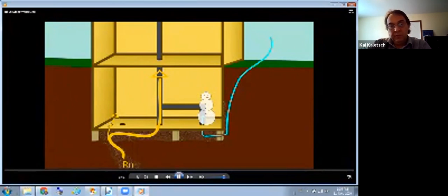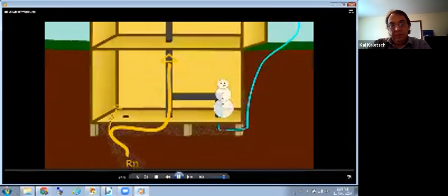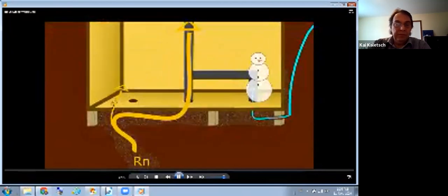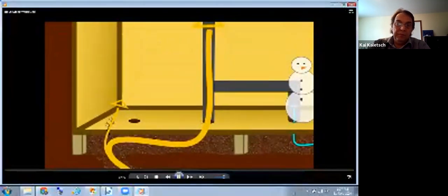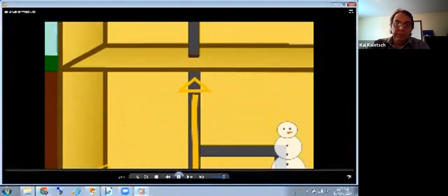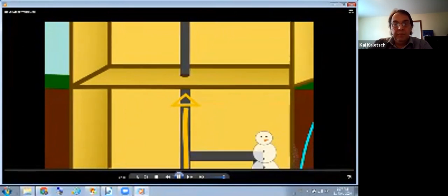Another consideration is that the mitigator may have depressurized the whole slab now, but what about 6 months from now when the water table is different? What about when the house's HRV intake is plugged, depressurizing the house? Maybe then the entire slab will no longer be depressurized with respect to the house. By sucking on the subslab, the mitigator could be bringing in more radon from below. So yes, the airflow through the crack is decreased, but there may have been an increased concentration of radon in that air.